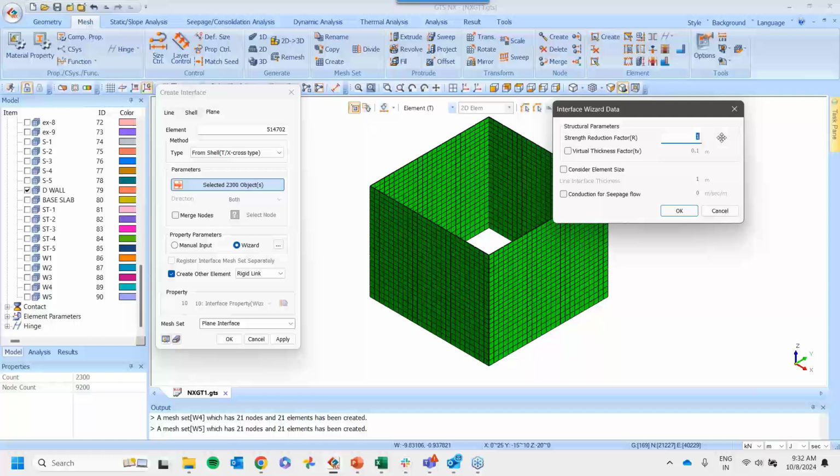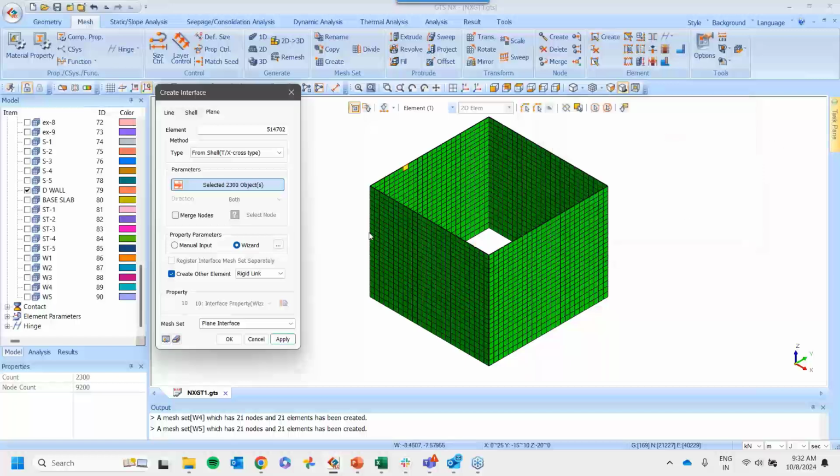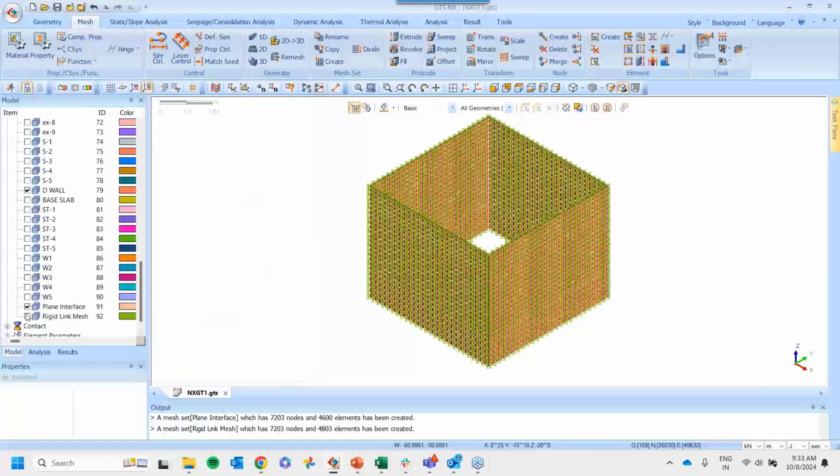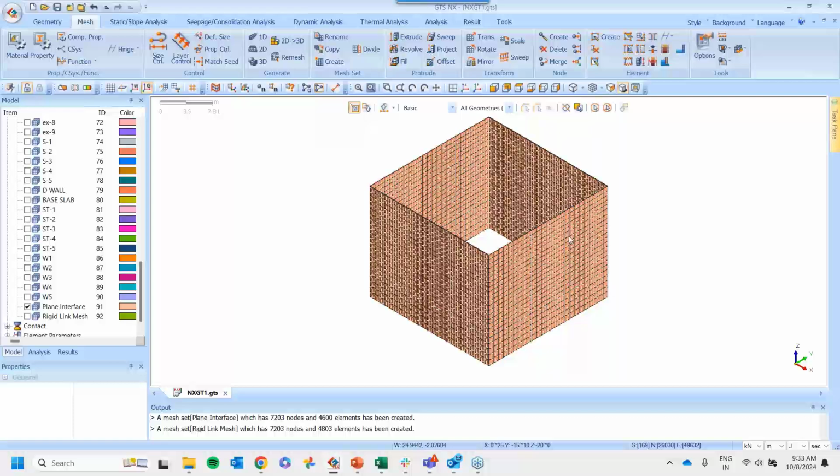And please do note, when we take non-linear interfaces, they are also elements with non-linear properties, which means they will have a finite stiffness. If that stiffness is breached, the model might diverge. So here I take a value of 0.7, press OK, and I'll press OK. It will take a couple of seconds. You can see my interface.